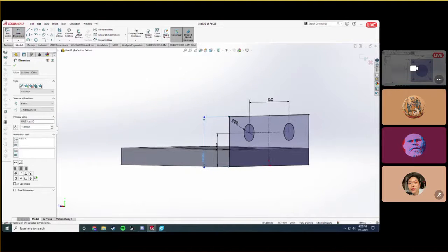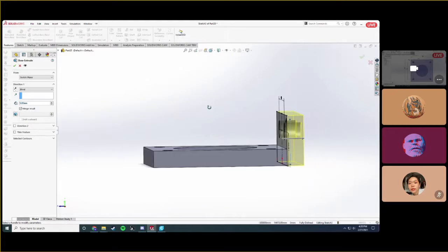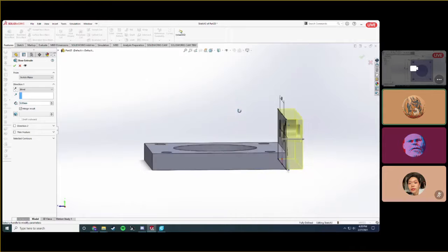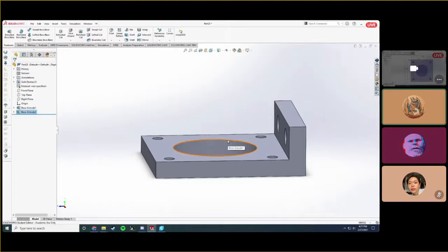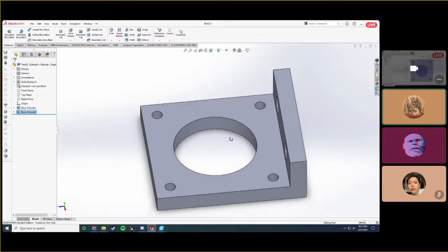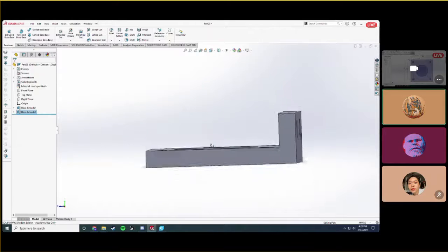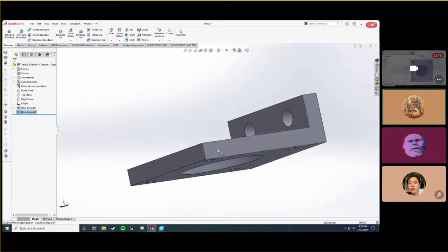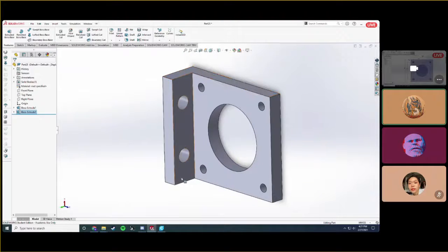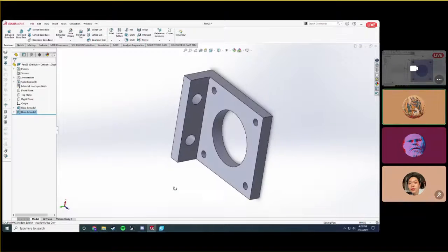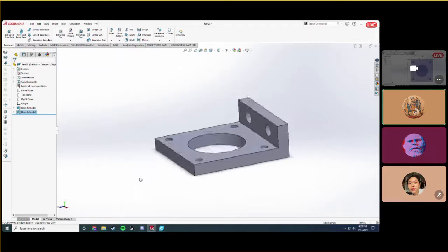Okay. Now come with another extrude. And I could leave it at 5 millimeters, sure. Now, let's say we were to 3D print this part, we could do it in a bunch of different orientations. Bottom, from the side. I'd probably print it like this just so the layer lines are the strongest at these corners. Well, I guess we'll get into that later. But just keep that in mind.